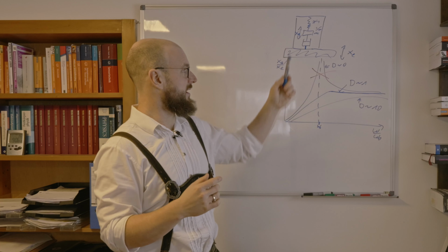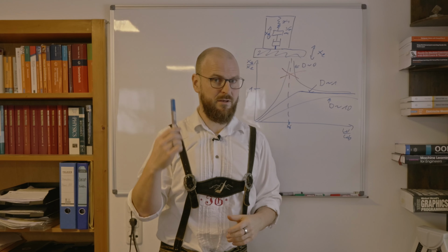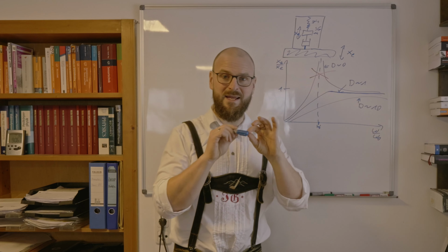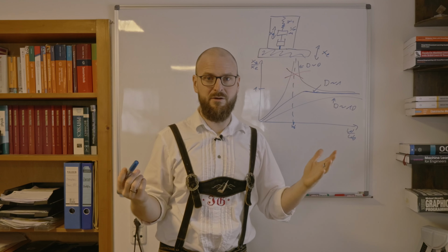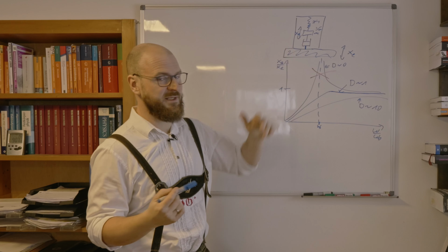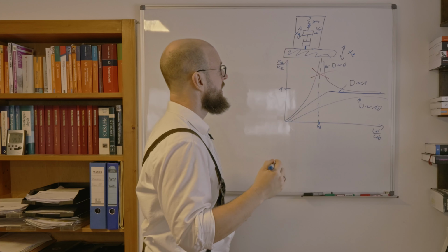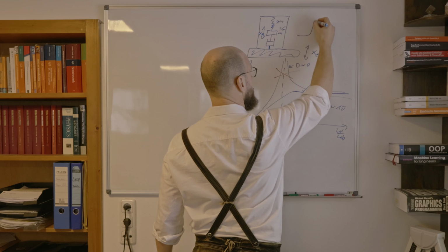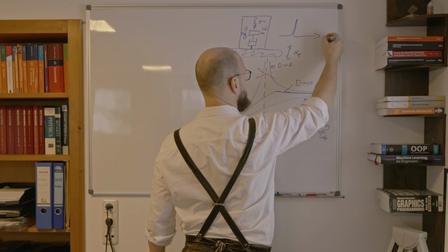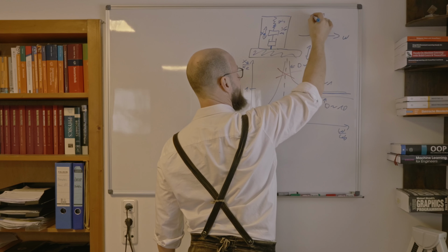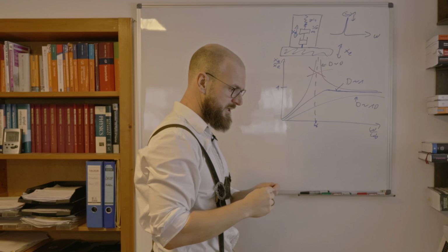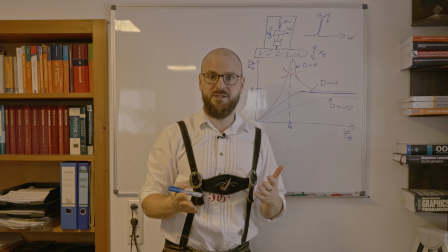So measuring the vibrations is something like hearing, but indeed we get an exact spectrum, not just the feeling of a hearing, but a real measurement spectrum. And now, for example, we can look for certain peaks in the spectrum of a measurement. And now if that peaks gets smaller or larger or changes its position, we know something changed in the machine.